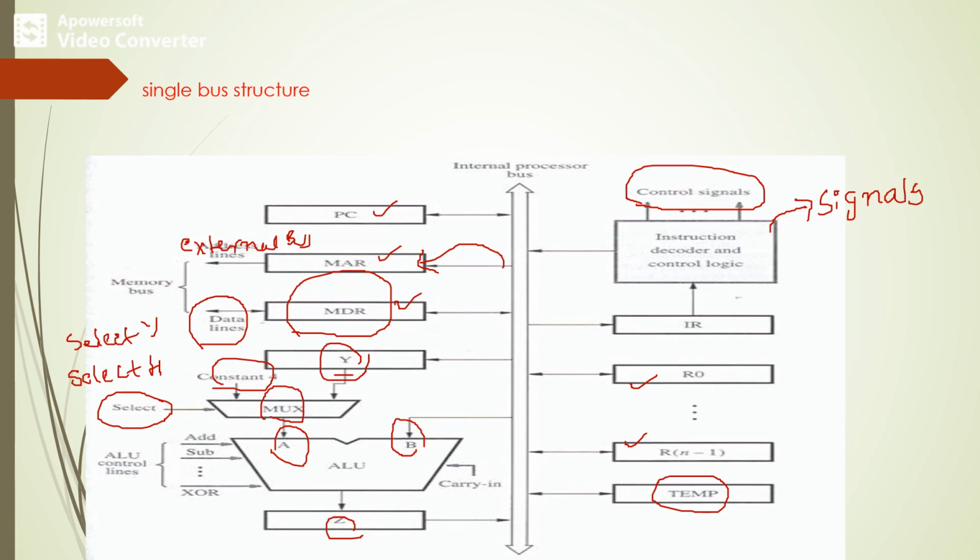The registers, the ALU and the interconnecting bus are collectively referred to as the data path of the processor. The instructions are usually categorized into three classes: memory reference, arithmetic and logic operations, and branch instructions. The actions required to complete an instruction depend upon the instruction class.